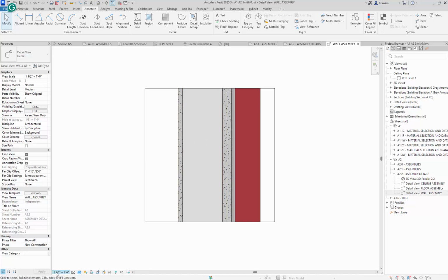And when you get to the scale, which is set to 1.5 inches, which is a detail level scale, what we want to do is go in and insert some 2D things, because you don't really model to the 1.5 inch detail, because then you'd be modeling for the rest of your life.